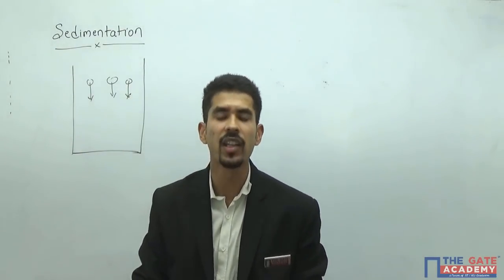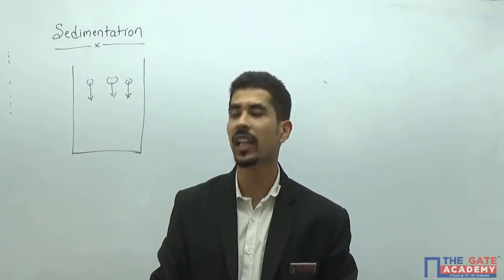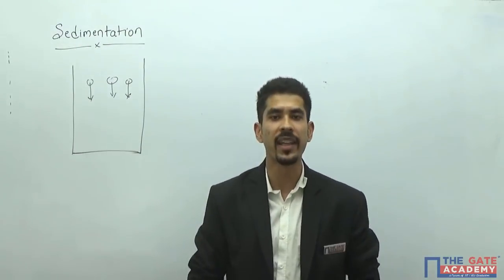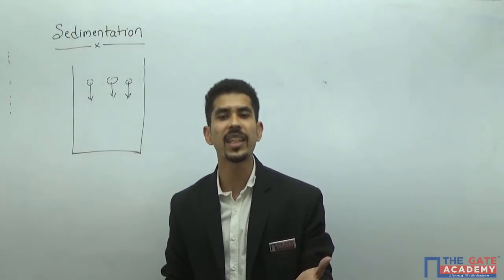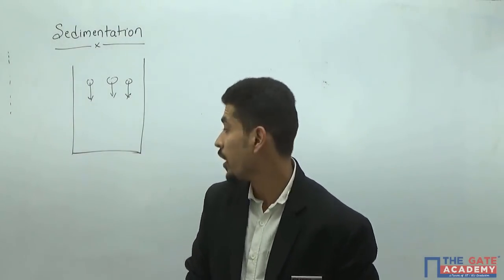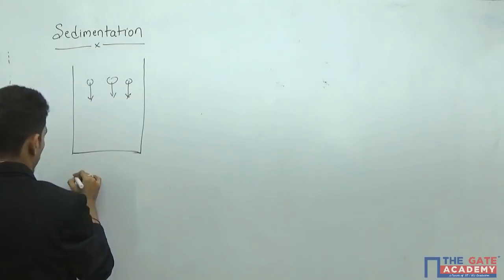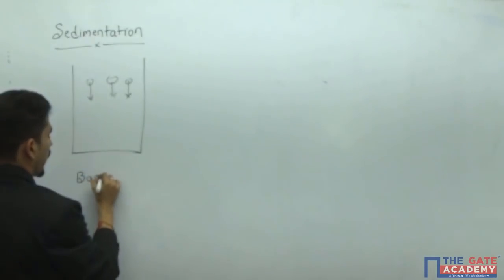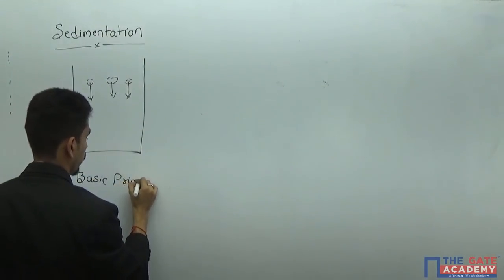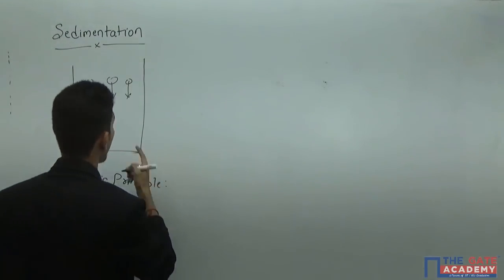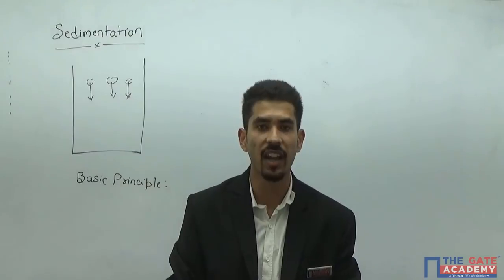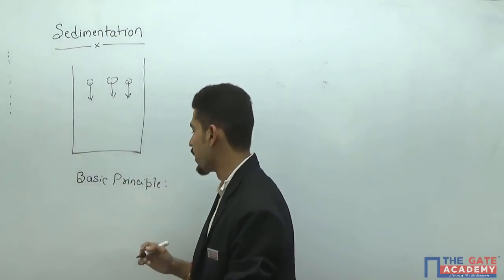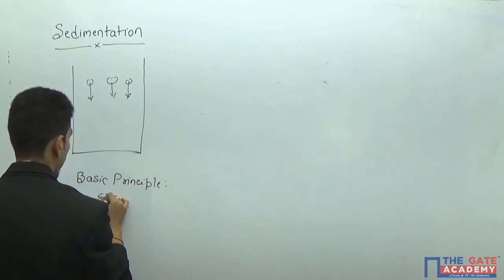So the weight is one of the most important criteria when we talk about sedimentation. From this concept, I'll take the basic principle for sedimentation. What is the basic principle for sedimentation? The basic principle is nothing but specific gravity.